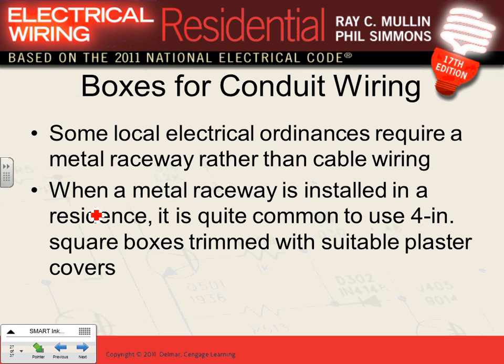We maintain 1.25 inches. People with a bigger screw can go right through the 1.25 inches that we maintain in the middle of it. So if you put EMT conduit in these walls, it's highly unlikely they can drill through. Is it more safe? Yes, but a little bit overkill. Why do they do it but we don't?